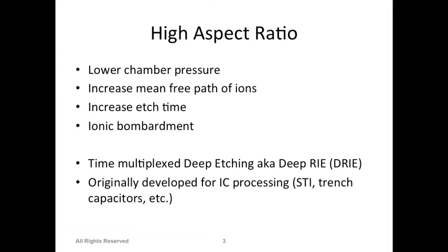Okay, so sometimes we want to achieve high aspect ratio features for a certain reason. One way can be anisotropic etching, where you can go much deeper inside. But sometimes we want straight walls, vertical walls, for a certain reason. In this case, the walls will be pyramid shaped with slopes. We don't want that. So we want the walls to be straight, most probably, and deep.